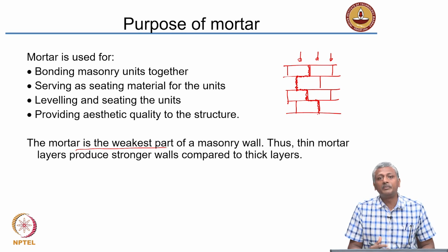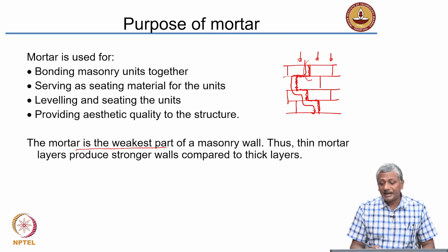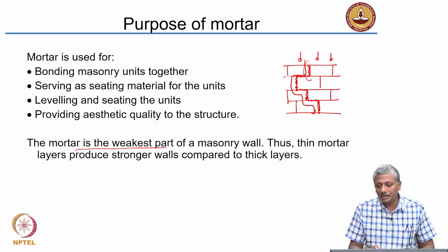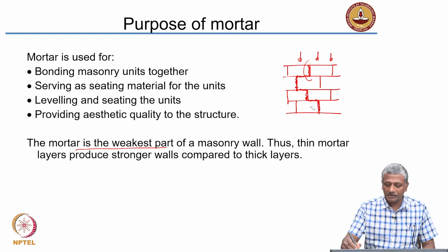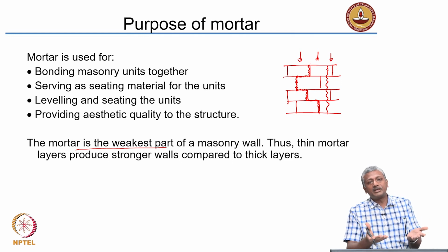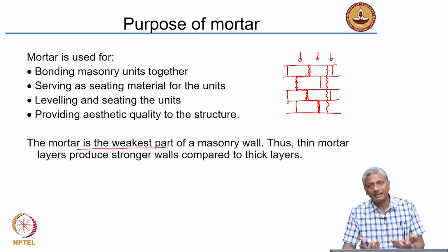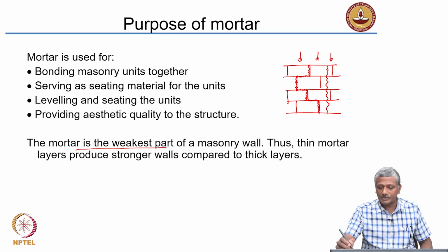Okay. So, the building will fail because of failure of the mortar joints, and that will be a slow and steady failure because the crack has to travel a longer path. So, it needs to come like this and come like this and like this and go. On the other hand, if the mortar was strong and the masonry material was weak, the failure would be completely different. You may have a cracking right through like this. So, entire building may just split into half because the masonry material, that is a brick or the stone, is weaker than the mortar. You have used a mortar which is very strong and it does not fail at all. So, you will get what is called a brittle failure.